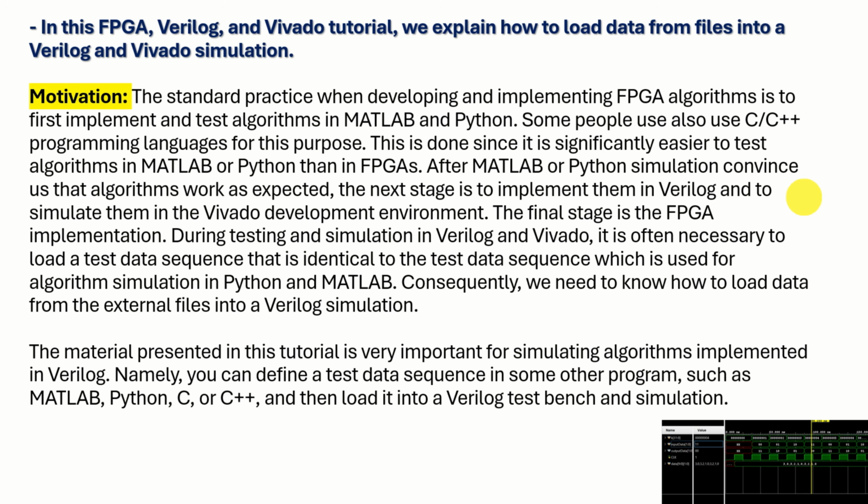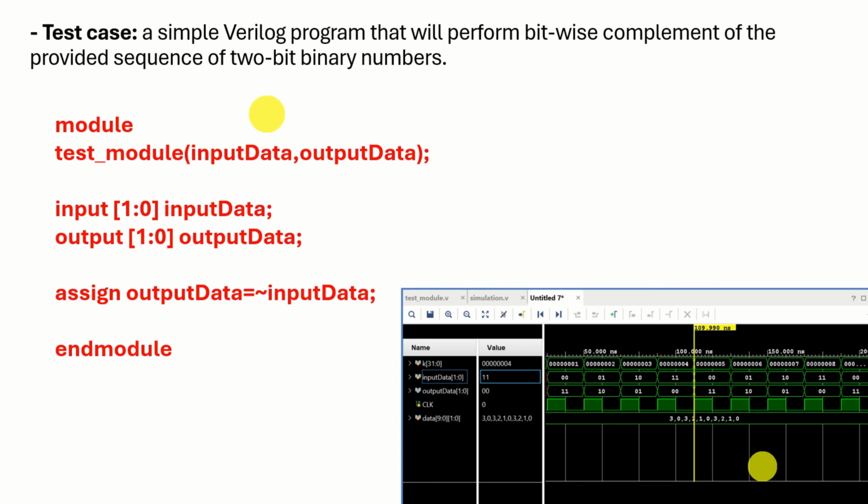The material presented in this tutorial is very important for simulating algorithms implemented in Verilog. In order to demonstrate how to load the data sequence inside of Verilog and Vivado, we consider a simple test case. Namely, we will design a simple Verilog program that will perform bitwise complement of the provided sequence of 2-bit binary numbers. And here's the module that we will implement.